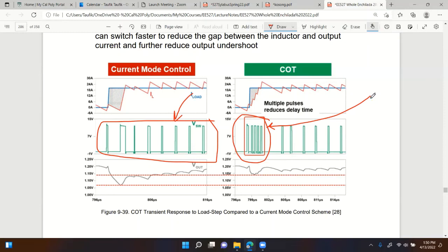Which means, related to the duty cycle, it is trickier to size the inductor, right? Because remember in EE410, we always size the inductor based on constant frequency, right? So what if the frequency is not constant? So then you base it off worst case, right?